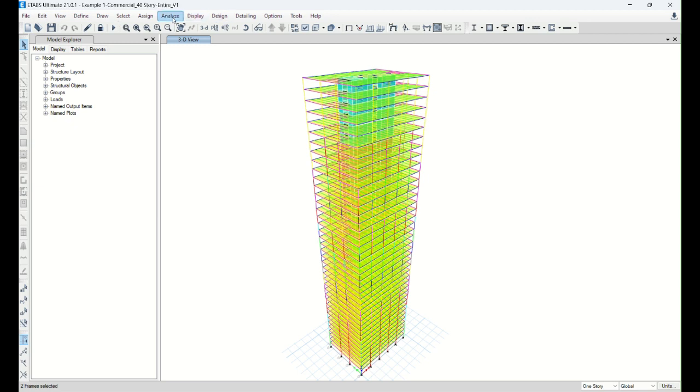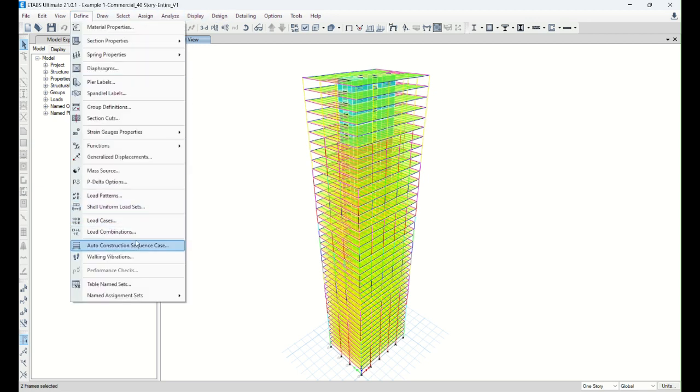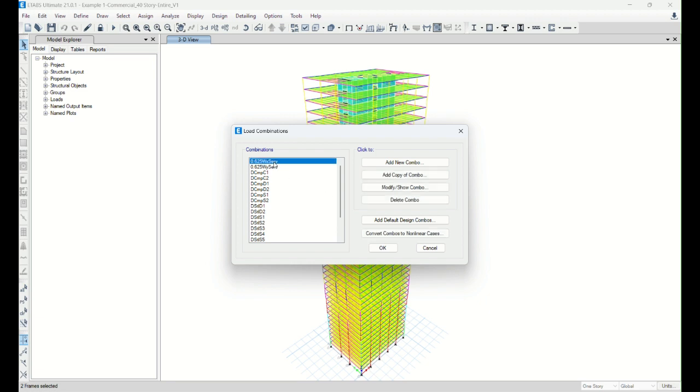The one thing I want you to make sure of is that the current ETABS version adopts the latest ASCE 7-16. They are using the ultimate wind loads. So when you define the wind speed, which is 117 miles per hour, you end up with the ultimate wind load. That is the wind load you're going to use for the overall strength design.